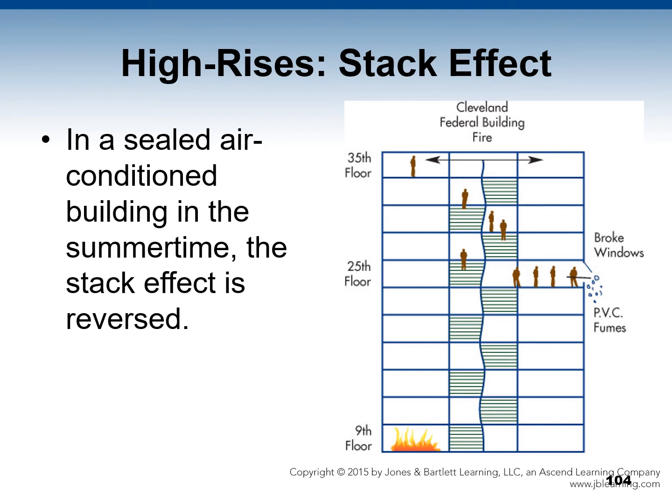In a sealed air-conditioned building in the summertime, the stack effect is reversed, where cold smoke falls downward. An example of that is a large fire that occurred in Norfolk, Virginia in a refrigerator plant. And I mentioned all of these instances offhand, but I again encourage you to research these fires. You learn so much knowledge, and you learn the lessons gained from these incidents that in turn have gone into improved standards for newer buildings, etc.